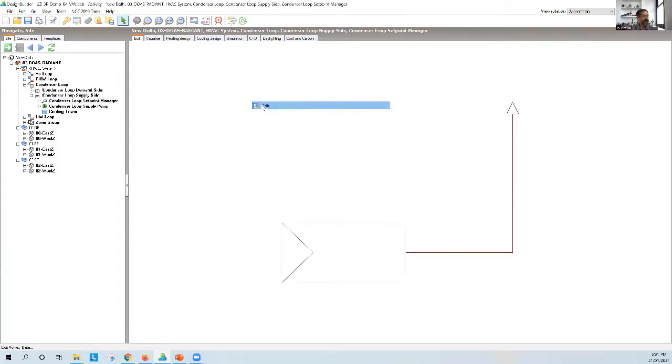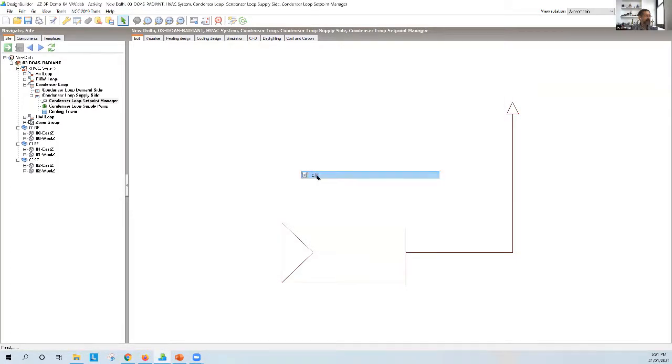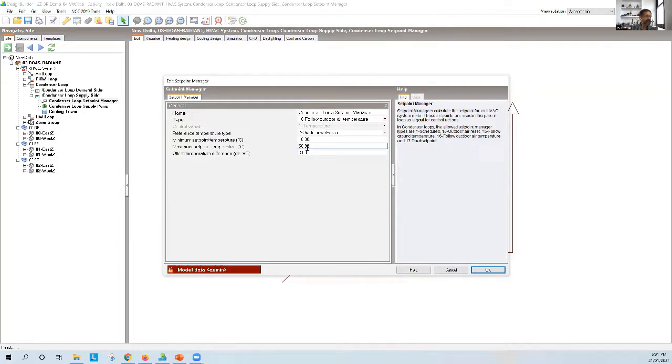Your set point manager for cooling towers, here you go. This is an interesting one. What it's doing is following the outside air wet bulb temperature and then trying to be about 1.5 degrees away from that. Again, that's pretty optimistic. I think 2 or 3 degrees between the outdoor wet bulb temperature is about as much as you can get to. And this minimum set point temperature is extremely optimistic. If you were doing 10 degrees, you're expecting the offset temperature to be 13 degrees. And at that point, you don't need a chiller. You need something to heat the system with. So I would say, you never really want to get below 20 degrees.